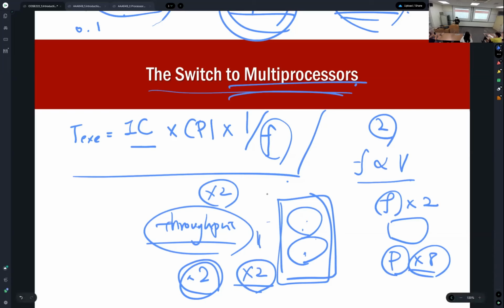It's proportional, because P equals alpha C V squared F. If we increase the number of cores, only C is increased because the area is increased. The capacitance is proportional to the area of a CPU, and if we add one more core, then the area is double. That's why the power becomes twice the original power.